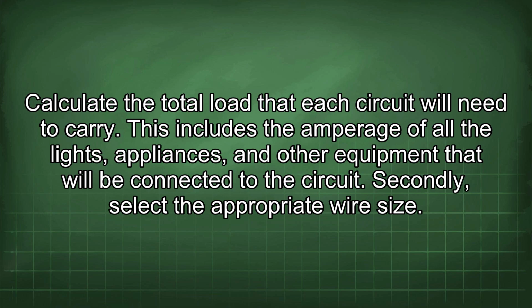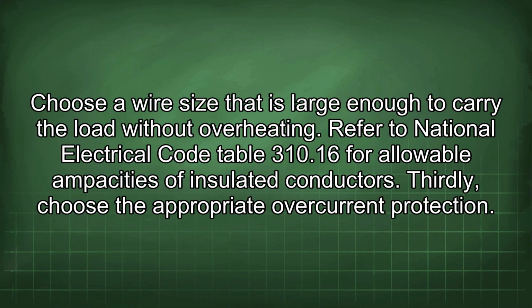Secondly, select the appropriate wire size. Choose a wire size that is large enough to carry the load without overheating. Refer to National Electrical Code Table 310.16 for allowable ampacities of insulated conductors.